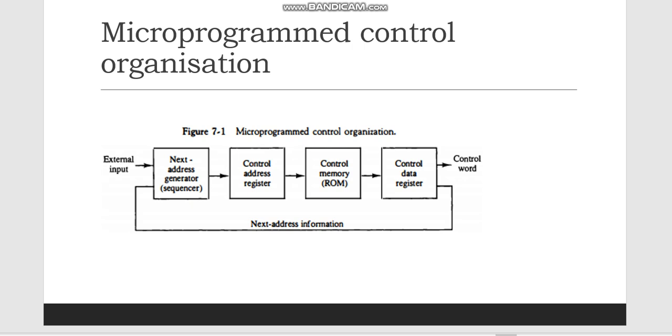A computer that employs a microprogrammed control unit will have two separate memories, a main memory and a control memory. The main memory is available to the user for storing the programs. The contents of main memory may alter when the data are manipulated and every time that the program is changed. The user's program in main memory consists of machine instructions and data. In contrast, the control memory holds a fixed microprogram that cannot be altered by the occasional user. The microprogram consists of micro-instructions that specify various internal control signals for execution of register micro-operations.